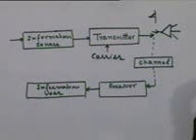Typically, not always, a carrier is a pure sine wave signal of a suitably high frequency. Why high frequency? So that it is easy to design an antenna which will be able to radiate it.